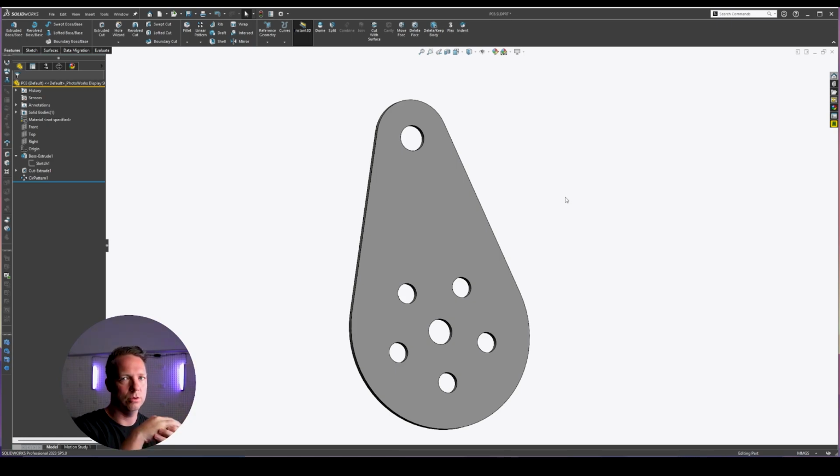If the shape that you're patterning has, let's say, a lot of curves and cuts or shapes to it, and it's not just a circle, maybe it's better in a feature pattern. Also, the feature pattern has a few more parameters that you can select and change. The feature pattern does not necessarily need to be a cut extrude feature. You can actually pattern like a face or a body or a surface as well, and that's what makes it a little bit different to the sketch option.